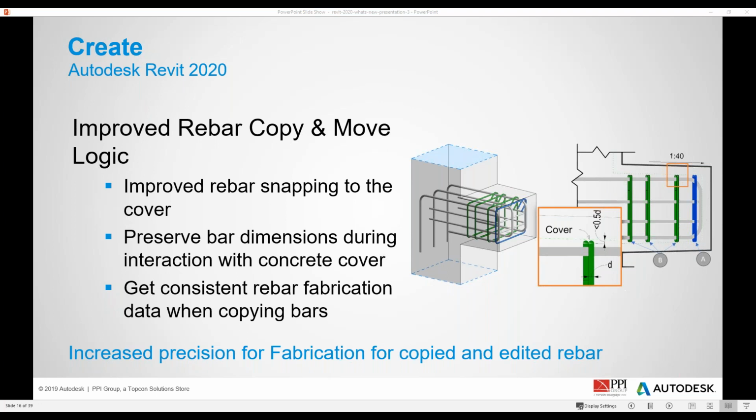Okay, your shape-driven rebar segments are now automatically constrained only to the concrete host faces that are in range of each segment. This change in behavior is going to ensure that bars will no longer incorrectly connect to faces that are far away and react to the changes of those faces. Now you can still manually select any face as a constraint target parallel to the bar segment, even if that face is not within the range.